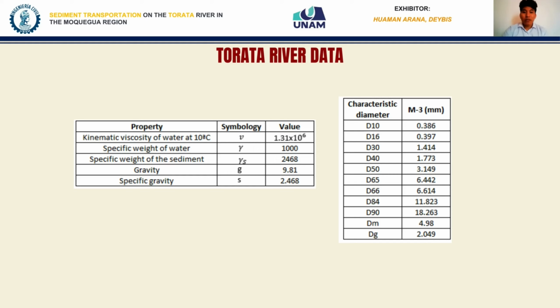The specific weight of the sediment is 2468. The gravity is 9.81. The specific gravity is 2.468. Characteristic diameters: D50 is 3.149 and the diameter of 90 is 11.263.